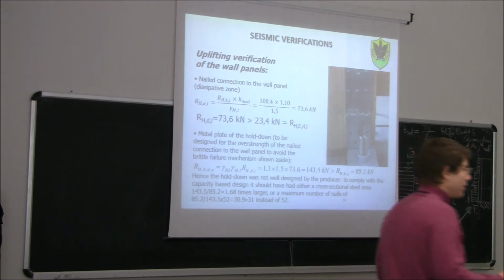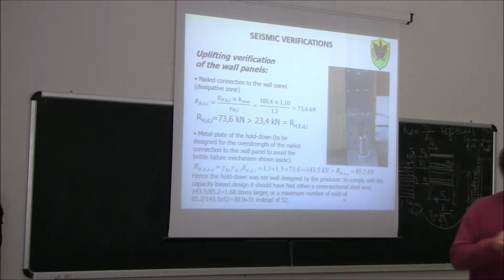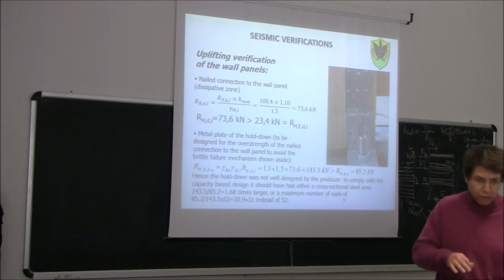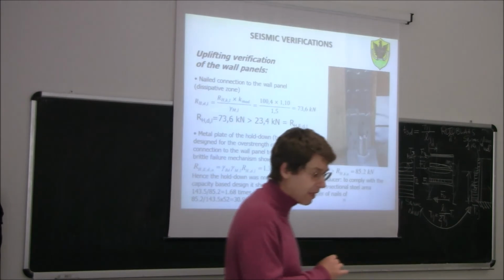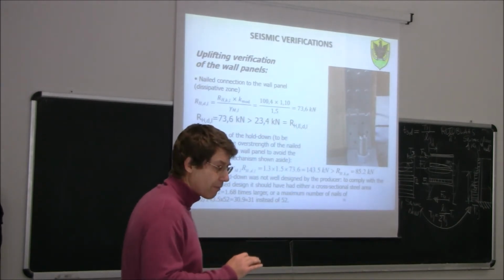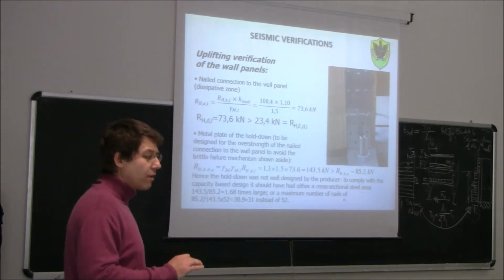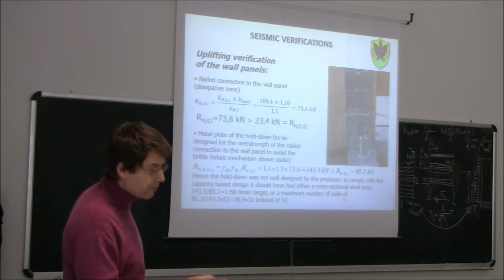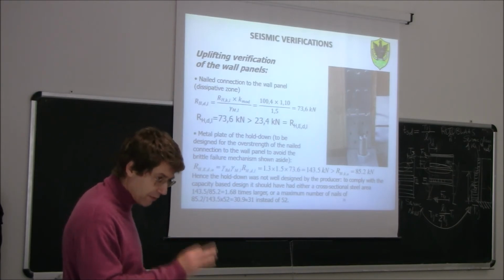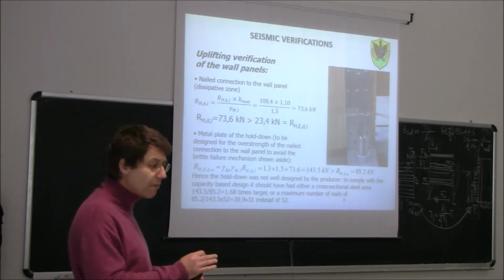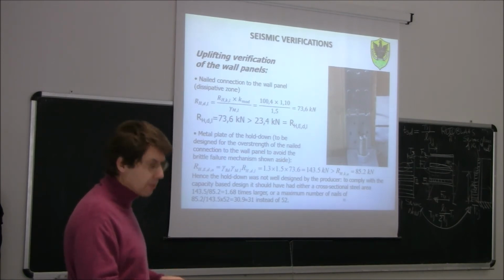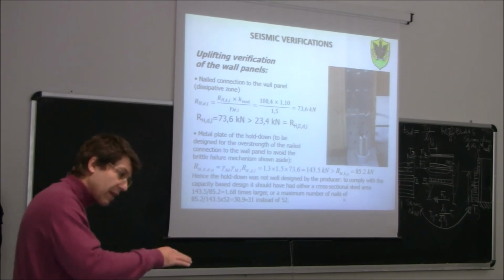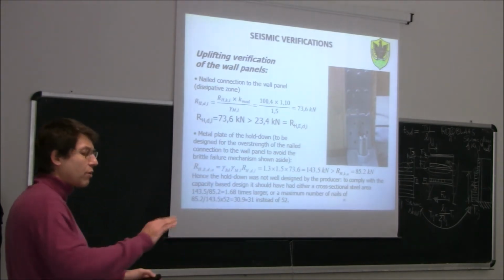But at the material level, if I do a verification on the cross-lam itself, for example compression on the cross-lam or bending of the cross-lam, then I can use 1.45 instead of 1.5. Okay? It depends which timber. If it's solid timber, it's 1.5. If there is glulam and cross-lam, 1.45. Exactly, yes. But only at the material level, not in the connection. The connection is always 1.5.